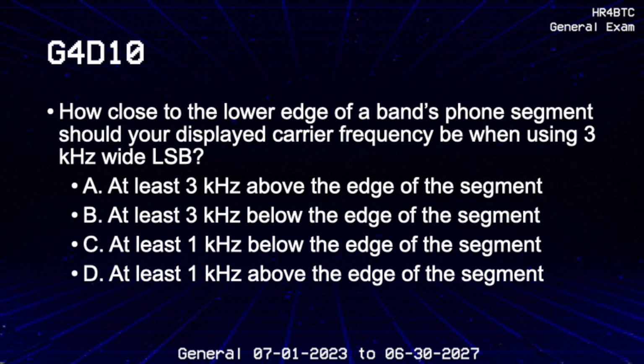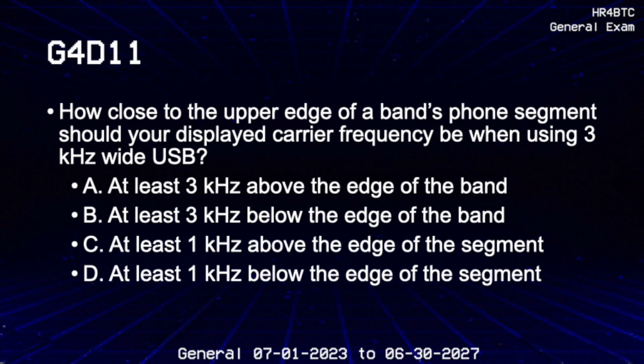How close to the lower edge of a band's phone segment should your displayed carrier frequency be when using 3 kHz wide LSB? At least 3 kHz above the edge of the segment. How close to the upper edge of a band's phone segment should your displayed carrier frequency be when using 3 kHz wide USB? At least 3 kHz below the edge of the band.